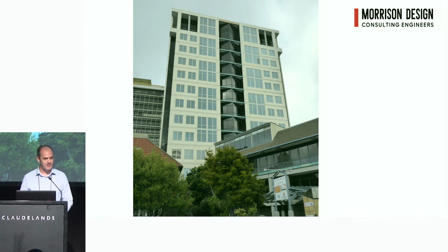But when we went and inspected the building, we found that actually this is just a precast facade. The main structure is set back quite a bit from this facade, so attaching brackets to this wasn't going to work out, and we ended up going with a different methodology for our design.